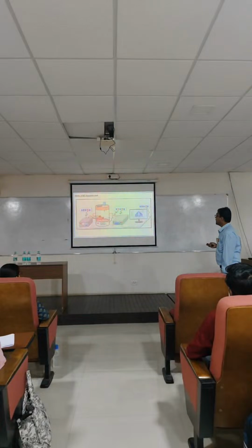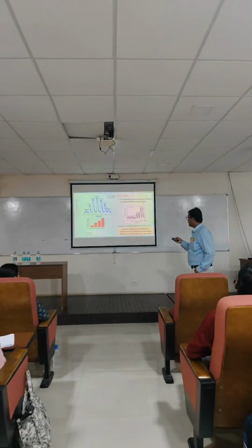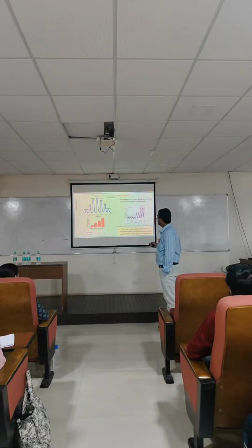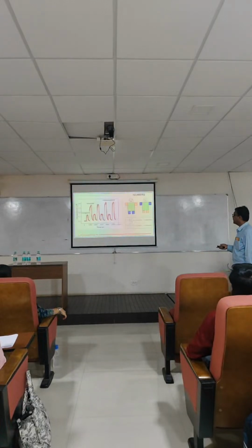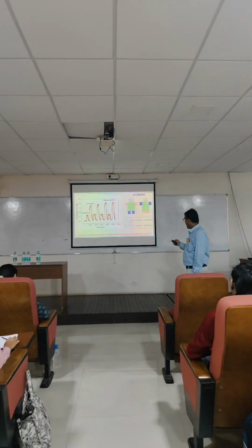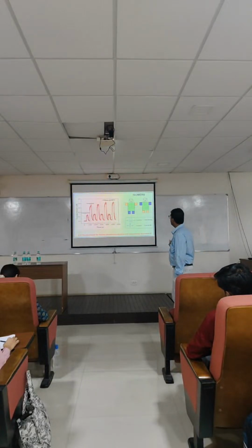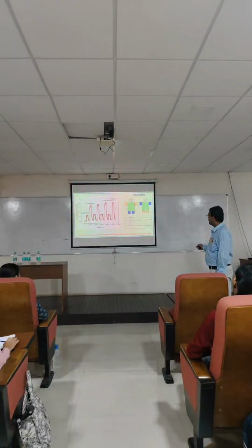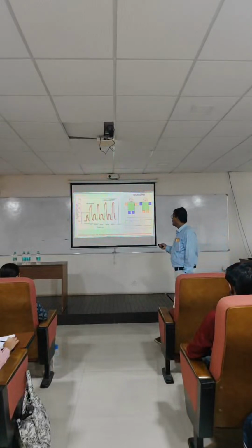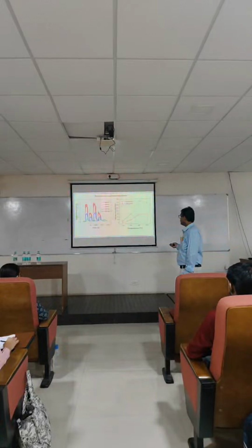These kinds of sensors can be tailored to monitor different kinds of gases as well. As you can see here, this is the different sensing system in the presence of methanol, ethanol, propanol, butanol. For these different gases, it can give you different sensing signals. But even when it is an isomer, meaning the masses are the same, you can also detect these using a sensor, like 2-propanol and 1-propanol. The masses are the same, but it can be tailored to give you this kind of sensing signal.